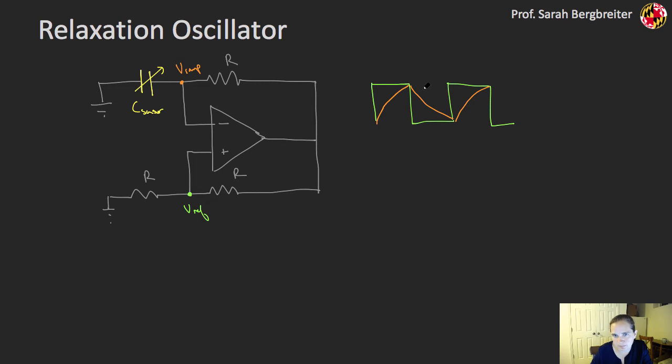So let's look at the case where this capacitor increased a lot. So my discharge time would be a lot slower. So it's going down, down, down, down, and finally at this point does my Vref become larger again, and now I bump up. So you can see how my frequency of this has changed. And if this takes a similarly long time to bounce all the way up again, this is going to stay like this. So I'm basically measuring this frequency here.